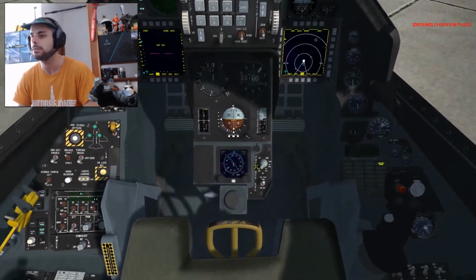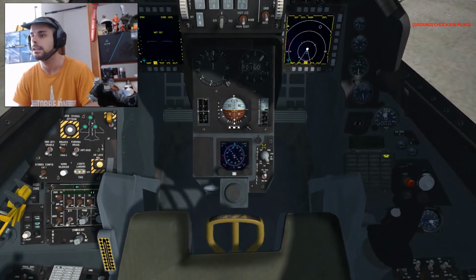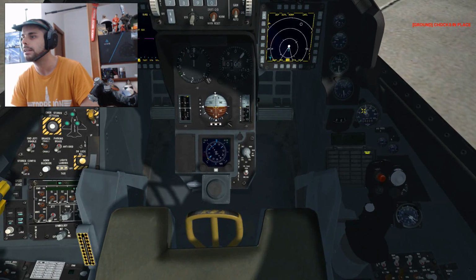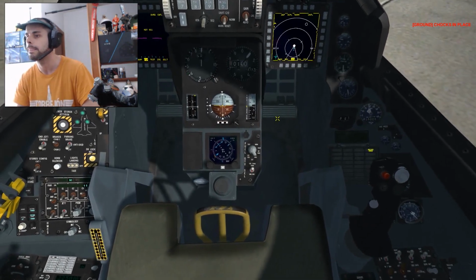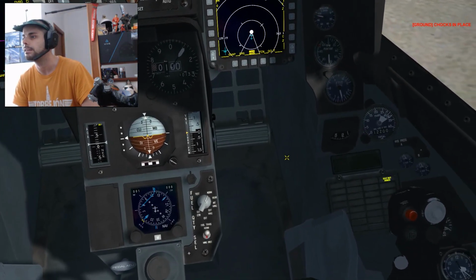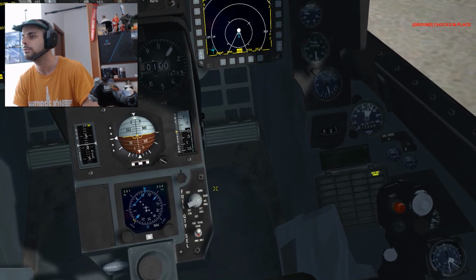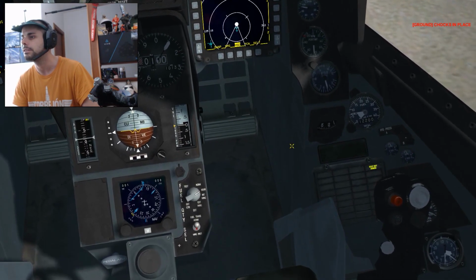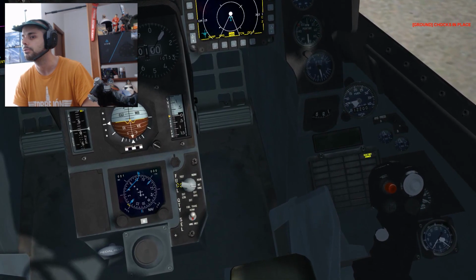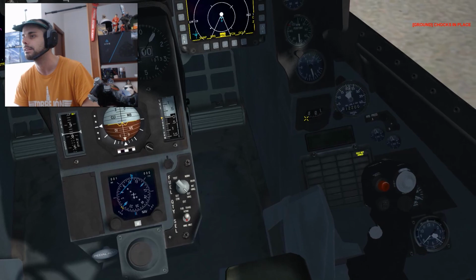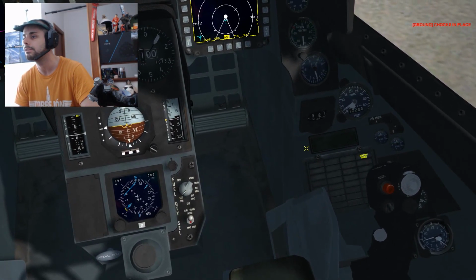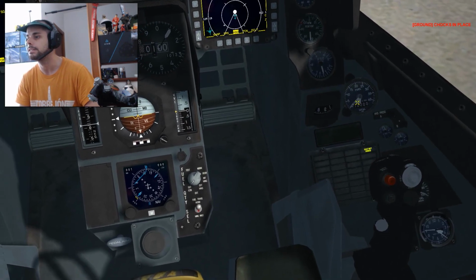And other test that you can perform is the fuel test. Here you have to set 6,000, sorry, and the gauges almost on the top. And now check the fuel status in the different compartment. Normal is good, not imbalance. Reservoir is the same in both tanks. Internal wings is the same in both wings. External wings is the same in the external wings, tanks. External tank, there is nothing. Then the gauge is 0.